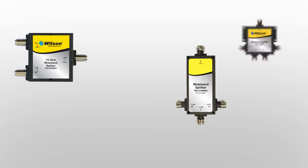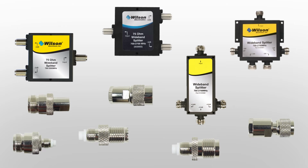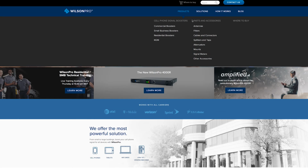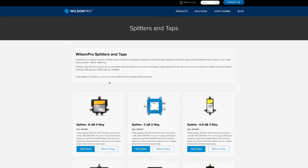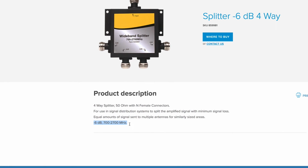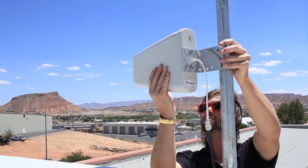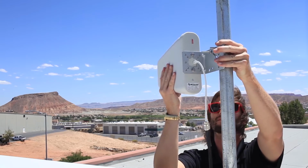There is also a loss when using accessories like splitters and adapters. Each of these accessories will state their amount of loss in their specs. You can find this information on our website or in the packaging for the accessory. For example, a 4-way splitter has an additional 6 dB of loss. Add up all of your cable length loss as well as loss from accessories and you'll have your total system loss.